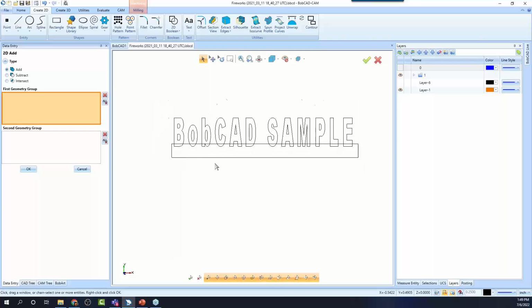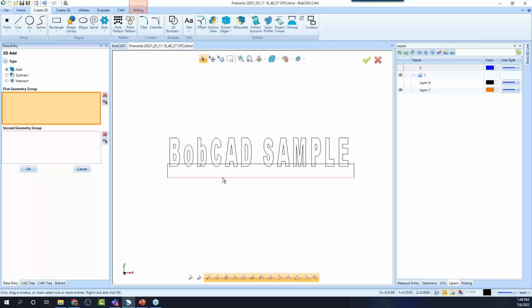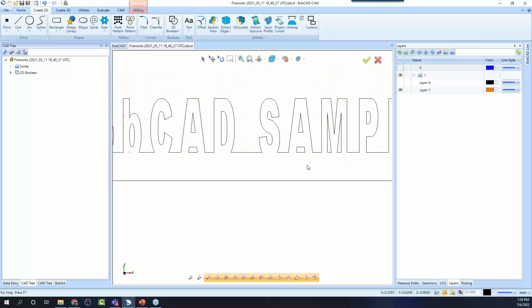Now, I just want to select the letters, but you can see that they're intersecting. So I'm going to shift click the first shape here, and then I'll window pick, because you have an inverting selection. I select what I don't want to select first, which was easy as a chain, and then I window pick and it inverts. Essentially I pick the first group, which is that one, and then I have to click into this other window here to put focus. You can see how it changes focus. If I'm in this group, it's focused. Change your focus to this group. We're going to shift click on that chain. You can see we have a preview. We'll say okay and cancel, and you can see how that connected everything there.